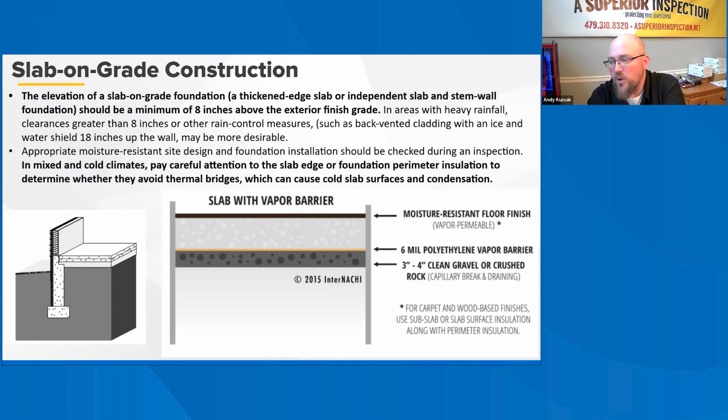Building codes typically require a capillary layer below the slab, and this should be provided under the vapor barrier so that water cannot be trapped in the gravel layer between the vapor barrier and the slab. The vapor barrier will help to cure the concrete properly if it is properly damp cured on the top surface, by preventing exposure to excessive drying conditions and ensuring that excessive water in the concrete mix is avoided.